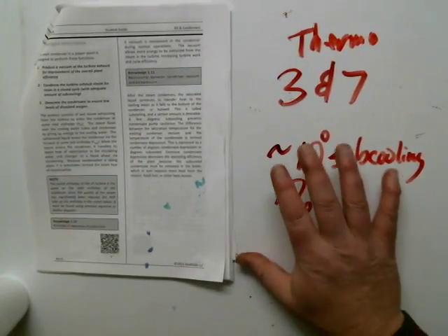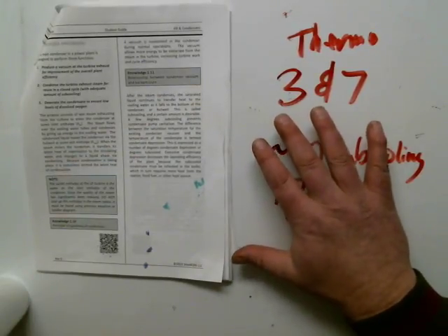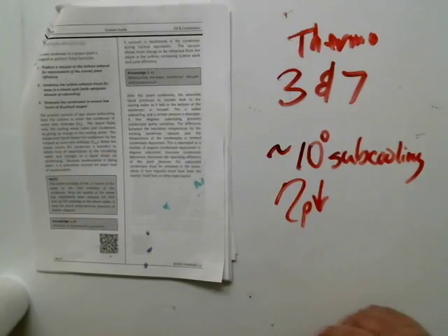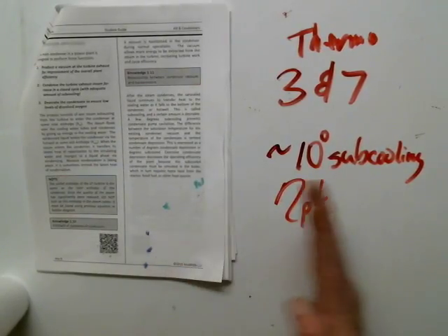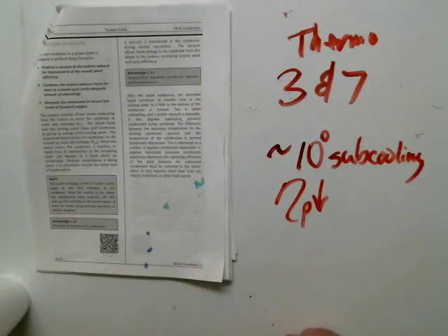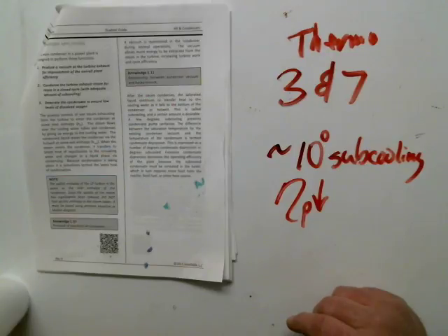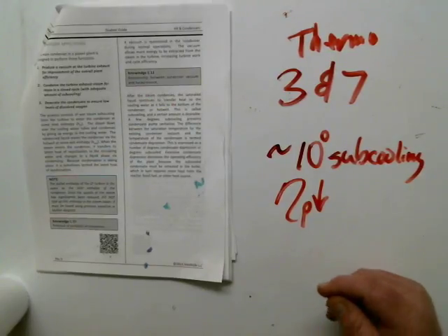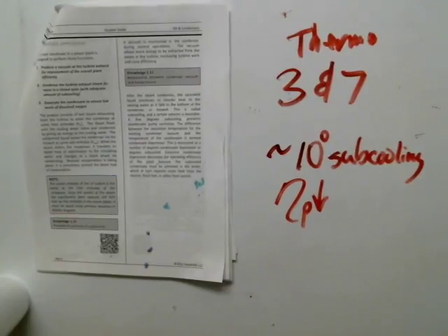Okay, this should really be a discussion about the components and how the condenser is made up of an inlet water box, an outlet water box, 2 tube sheets, and with the tubes going across the condenser. And I'll tell you, we generally put feed water heaters, low pressure feed water heaters in the neck of the condenser because it just makes sense from an economic standpoint. But we'll talk about that later.